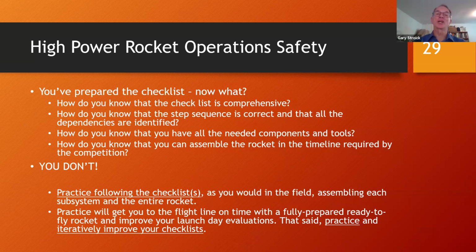Just like you go out and test your ejection charges to make sure that they're going to eject your parachutes, or just as we have you do a flight test before you come to the competition to make sure that your rocket's going to fly successfully, you need to check your checklists. And those are good times actually to test them. I would recommend testing your checklist before you do your flight test, by the way. Somebody should be noting, when you're doing these tests, where are the checklists missing things? Where are they not in the correct sequences? What do we need to do to fix it? And so on, because you don't really know that they're working yet.